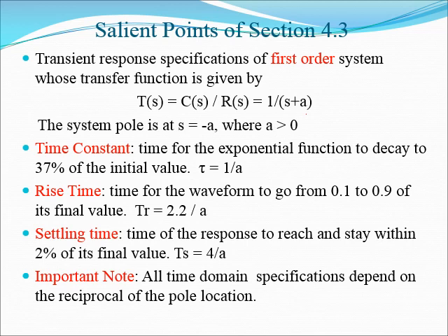So rise time is the time for the waveform to go from 0.1 to 0.9 of the final value. For example, if you take a step response of the system, the step response goes like this. So 0.1, let's say this is 0.1.